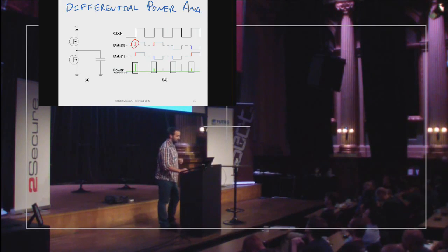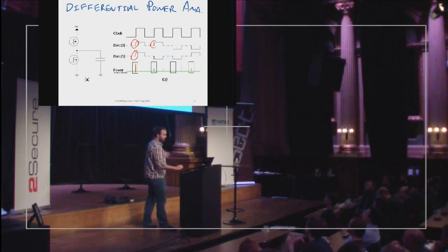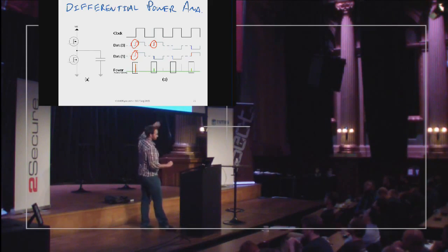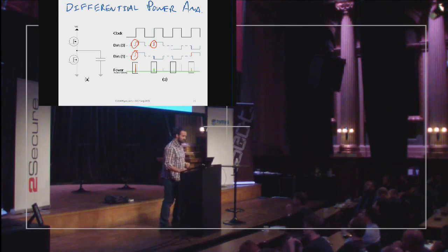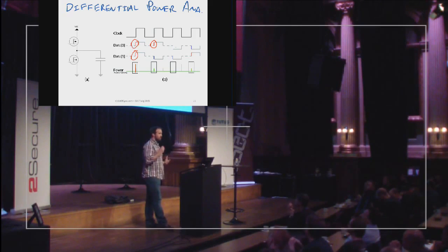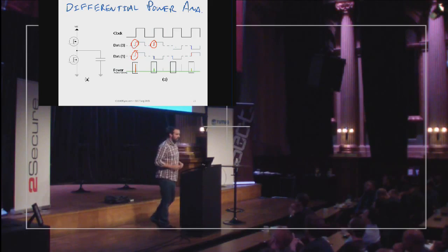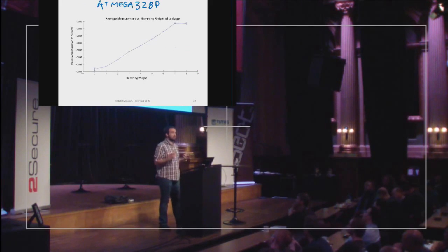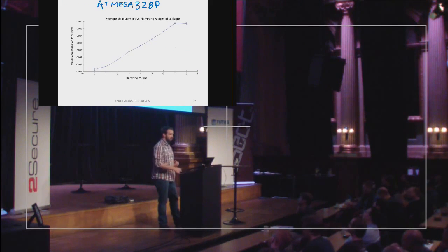data bus? So if 2 of those data lines are switching to high, we actually see a larger spike than if just one of those data lines is switching to high. Or if neither of the data lines are switching to high. So if they're switching low, we won't see this positive spike at all looking on one of the power rails. So what this would suggest is that the power consumption at a very, very, very fine level is actually directly related to how many ones are going on the data bus, which seems crazy because we're learning quite a bit of information about the chip. And this is actually completely the case.